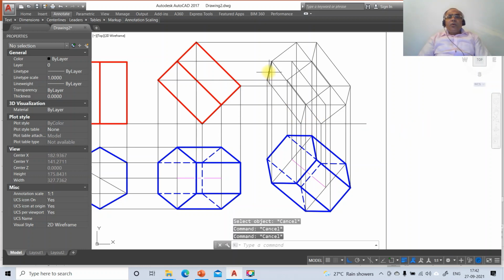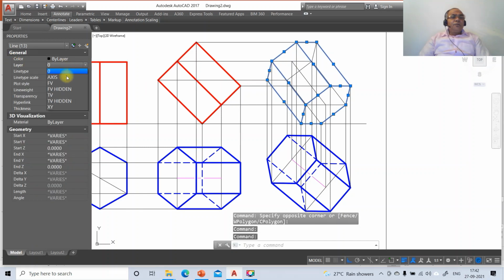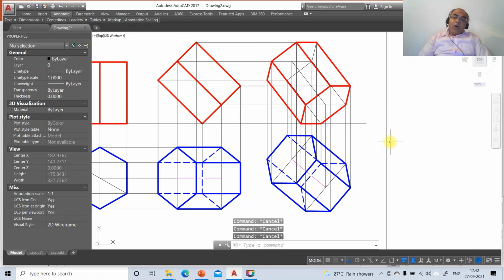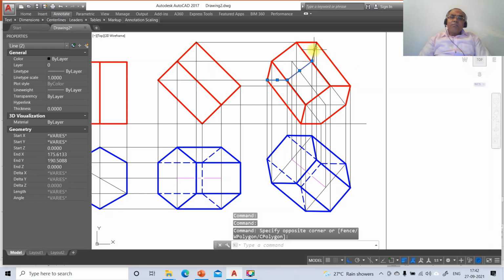Now here all the exterior edges of the boundaries of the solids are visible. Then the surface nearer to the observer is visible. Once you do that, which is the edge which is visible, so these two edges are visible. Go to front view and now the edges which become invisible are this line and this line and this line